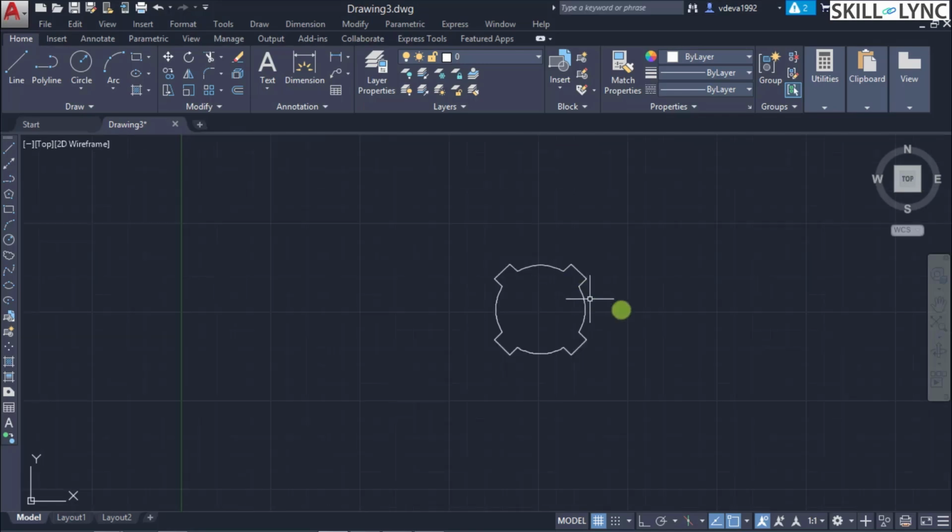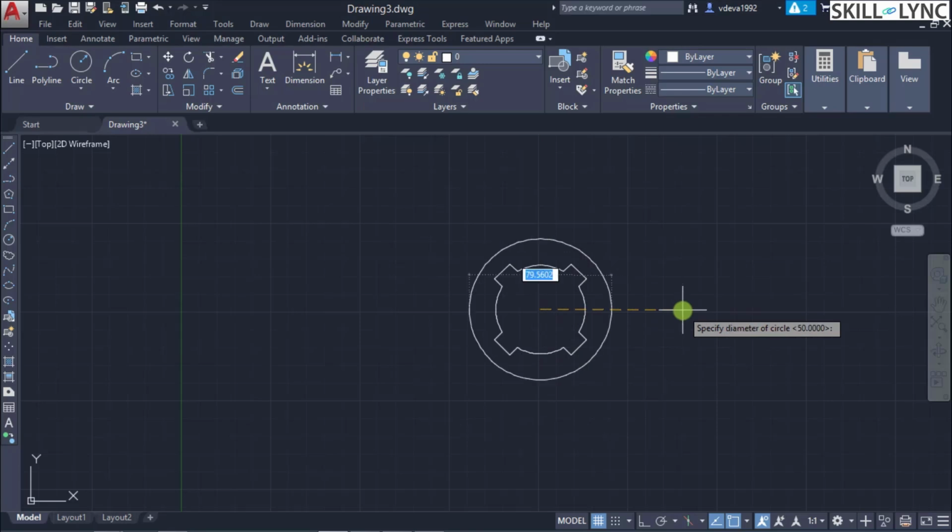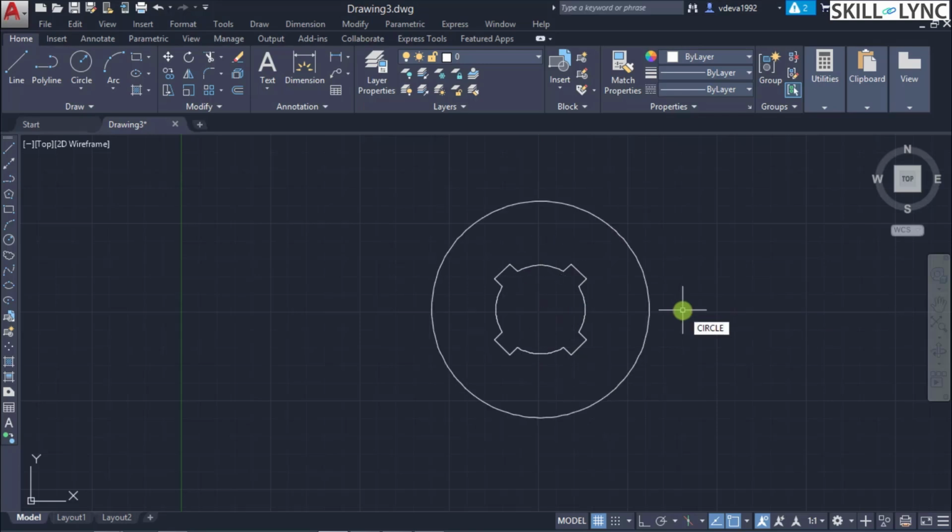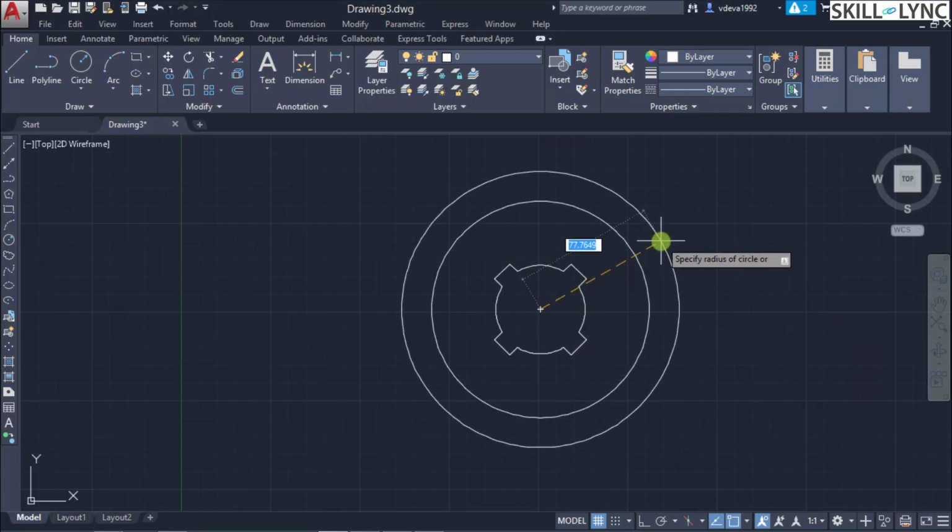So now let us go back and draw the external component. The next component we've seen is the slot area where the spring is going to sit in. The pitch circle diameter is the same as the inner circle diameter, that is the external slotted spring area, 122 mm dia, and the external circle is 154 mm in dia. So let us draw two circles for that, with the same center point, diameter 122, as well as one more circle with the same center point of diameter